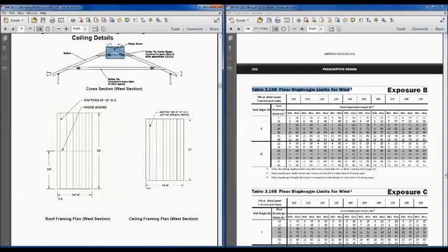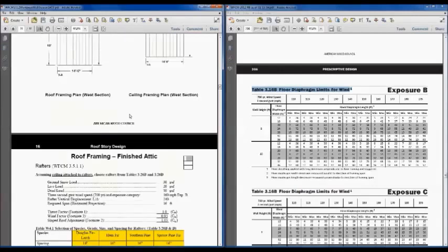Now, I don't know that they make hangers, fasteners that would allow you to connect the rafters to the glulam beam, let's say if you're using a ridge beam, that would resist that uplift force. It seems like that'd be putting the nails in withdrawal in those hangers if that's what you're using, and so that's probably not a good solution, but you have to check with the hanger manufacturers about that.